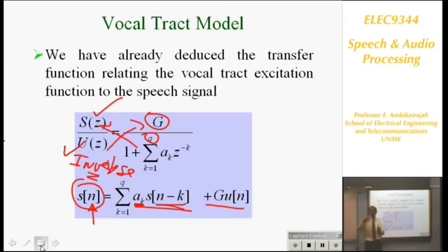So from the past samples, I can actually tell you what the current sample is going to be. That's what this equation tells you. The current sample is equal to the coefficients multiplied by past samples of speech plus the excitation modified by the gain. And that's very important. That's in the time domain; that's the z-domain, the frequency domain. You must be able to interpret this equation.